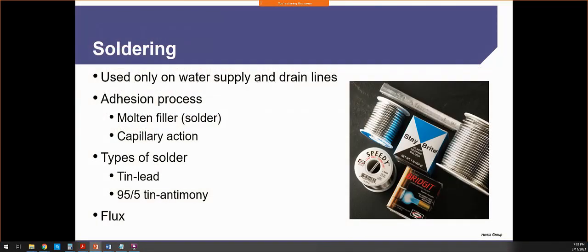When we're using solder, all right, actually let me backtrack here. When we're brazing, we're creating high heat, so the advent of using solder and stuff like that is not needed. So when we're using flux, I should say, when we're soldering, we have to prep our piping, okay? We have to make sure that our piping is going to stay nice and clean.